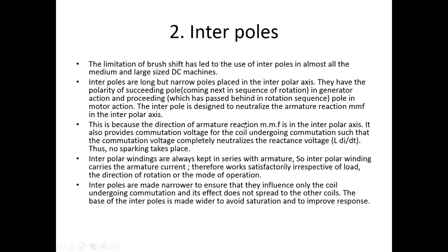To balance the armature mechanically, we place dummy coils in the armature winding. While designing the armature winding, we place the dummy coils. And one diagram also, how to draw lap winding, how to draw wave winding. All this will be in offline classes. In the offline classes, we will draw practically on the blackboard, based on the number of slots, back pitch, front pitch, and number of slots provided, we draw the winding.